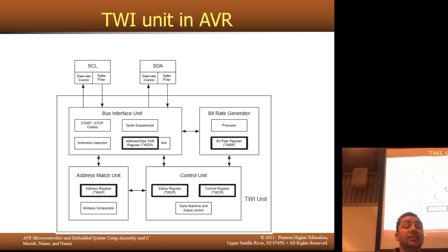Oh, look, there's an SCL line, an SDA line, an address, a start and stop condition, an arbitration detection. It's almost like this will do exactly the same thing as I²C, but not be called I²C. Funny how that works. Yeah, it's the same thing. It's just I²C compatible. So it's got a thing that will generate start and stop conditions. It's got some things for noise immunity, slew control, spike filter, spike suppression.